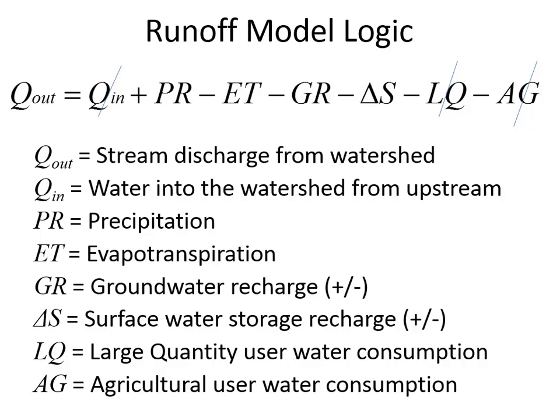There's a watershed, and what we'd expect is that over the very long term, we should be able to predict how much water is going to come out of the watershed simply by how much rain there was and how much evaporated. And that's taking a very complicated runoff model and making it very simple. But that's only valid over the long term. On a day-to-day basis, this model wouldn't be very accurate because there's a lot of individual variability that's happening on a 1 or 2 day basis.